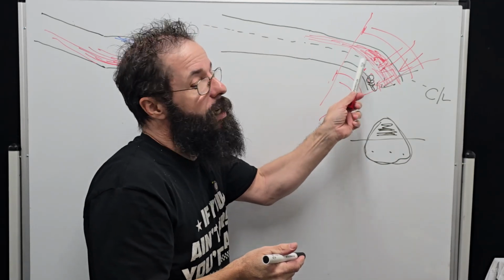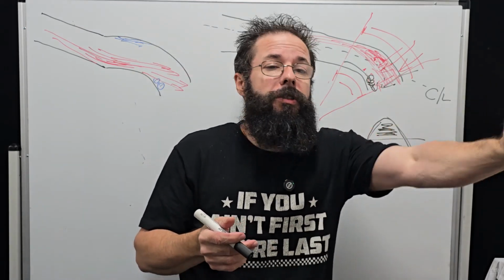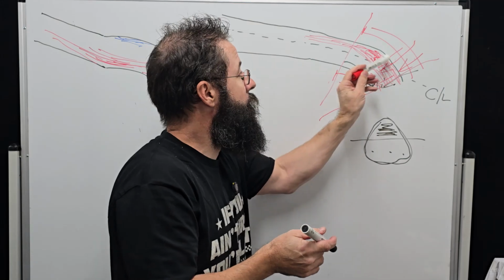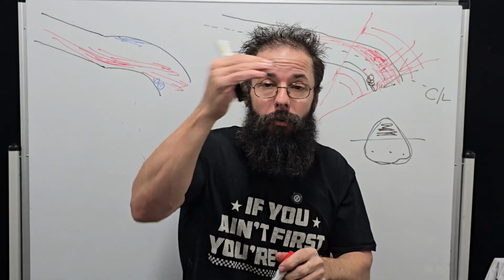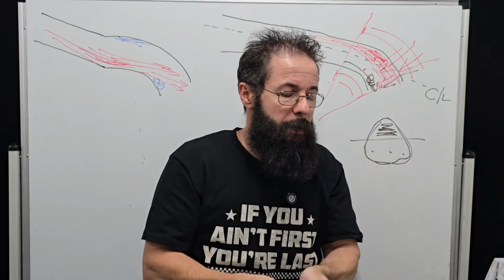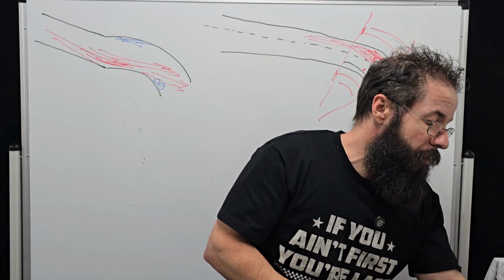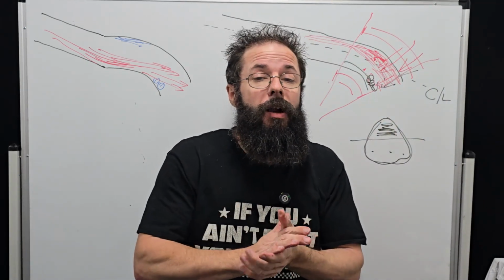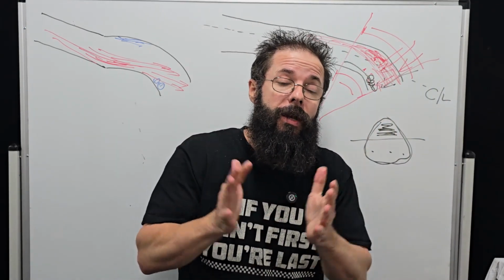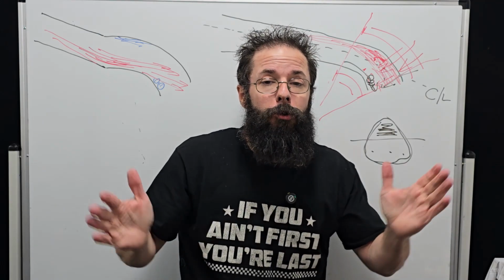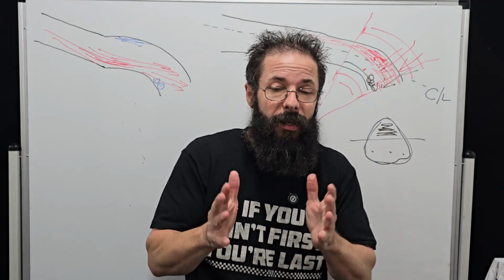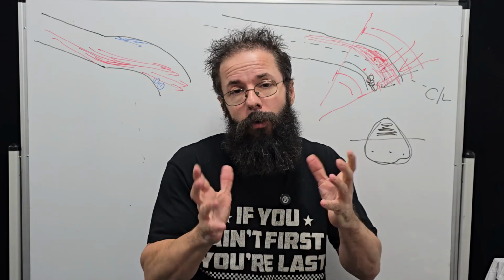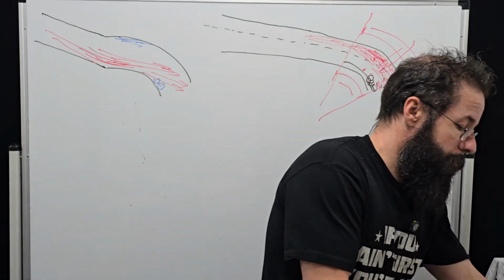When air is too quick on the short turn, that's when it just skips off because it's getting in front of the other part of the air on the roof as well. So we've got to look at that aspect as well. So I'll clean this off, and now we'll get into saturation points and why some cylinder heads turn to absolute crap at specific lifts or different things. Let's do it.